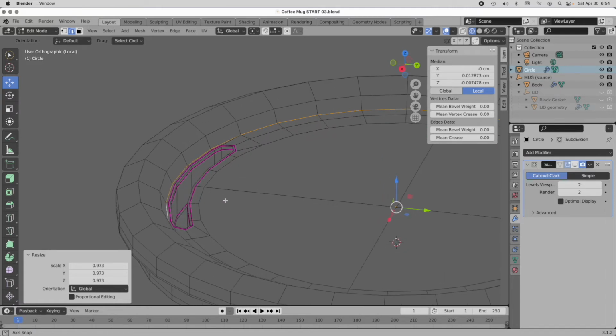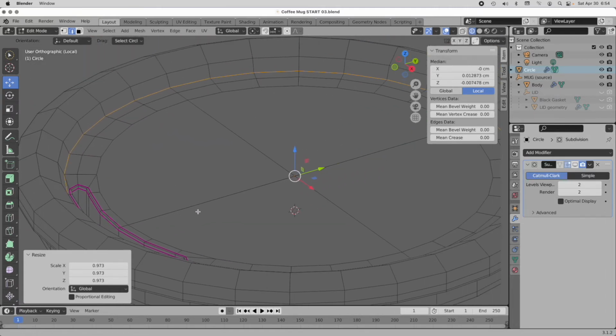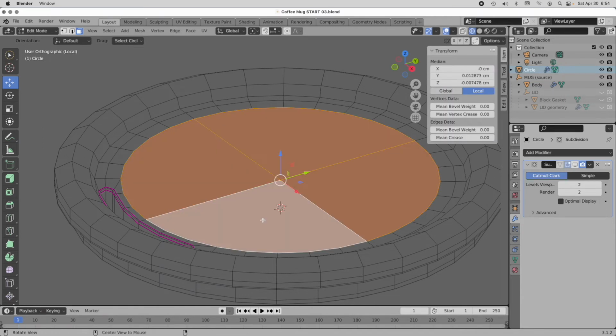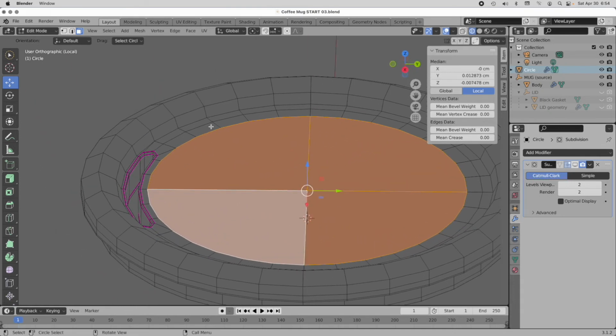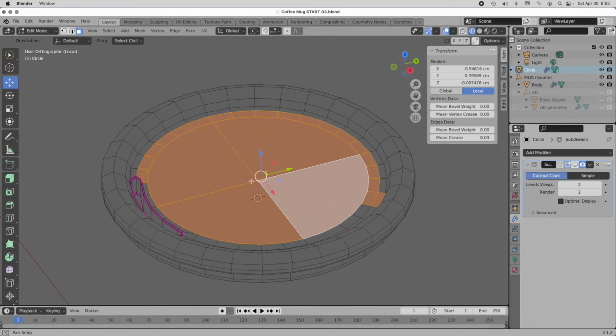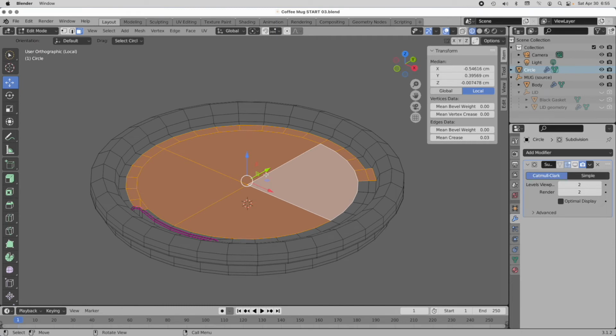It's really great. This is a planar region, and this is one of the things I always want you to be aware of: when you are working in a planar region, you have more flexibility with the configuration of your polygons. These are all planar to each other, and we created a planar row of polygons on the outside. All of these are planar. That gives us a lot of flexibility in configuring these interior polygons, or rather not exactly worrying how they're configured. Because when they're subdivided, all the subdivided polygons will also be planar, and you don't really need to worry about how pretty they look. And that's exactly the case here.